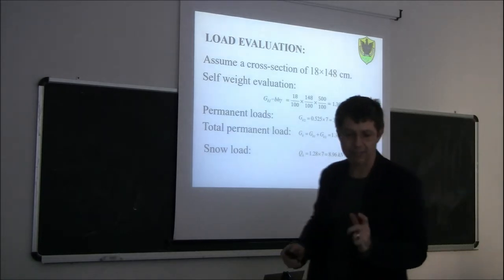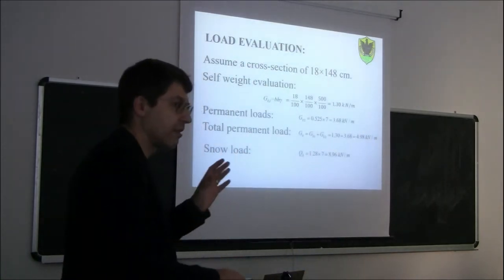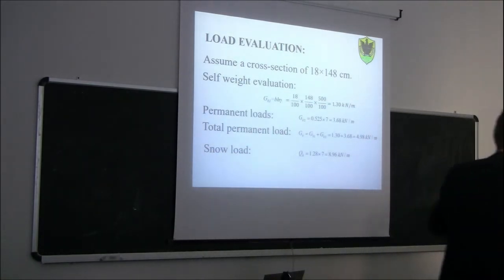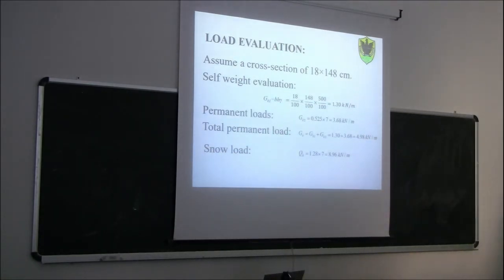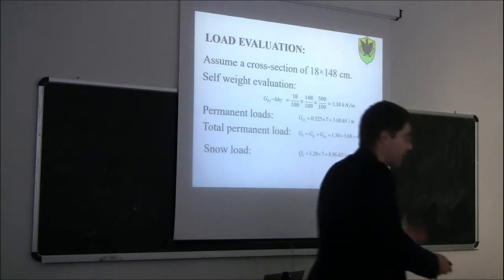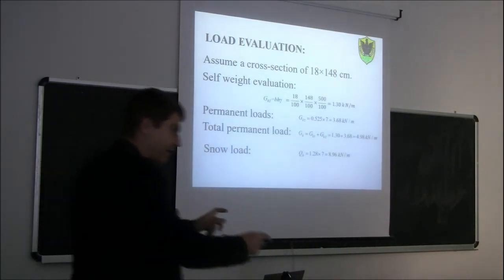That's why we said last time, or twice, I don't know, maybe some weeks ago, that timber structures are lightweight. And if you remember, I also told you that if there is an exceptional snowfall, it's most likely that we might have some problem with a timber roof, rather than with a reinforced concrete roof. Because with a reinforced concrete roof, the permanent load is very high, whilst here, the permanent load is very low. If you remember, we did a small calculation to demonstrate this, because it's not so obvious.